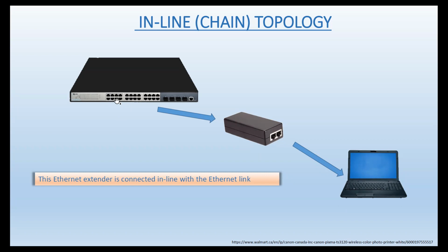many different kinds of switches. So some of the more expensive switches have the PoE capability on every port, which means every port is capable of sending and receiving data signals, acts as an Ethernet link, but also has a voltage superimposed on some of the pins or prongs that can power up equipment. So that can be powered up if the switch has ports capable of that.